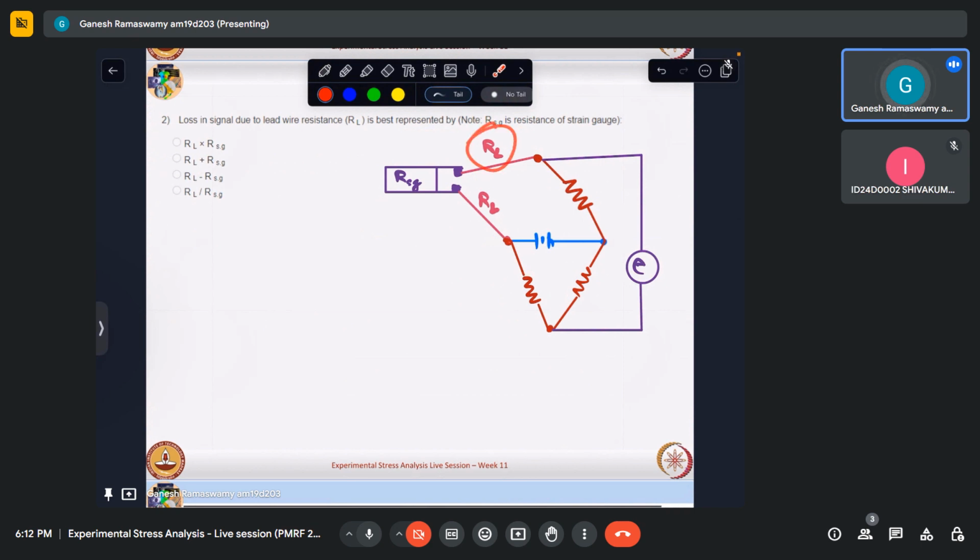So we will have to take that as the benchmark and proceed with it. And this brings in a lot of complications. For example, if I were to have this long wire and I go and touch it with my hand, we impart some heat and that changes the resistance. If you are making many minute measurements, that also will contribute to a strain which is actually not brought about by the mechanics of the problem that we are trying to study.